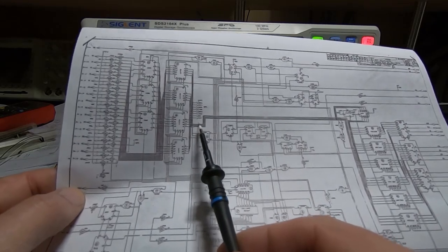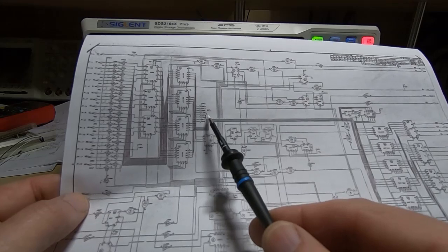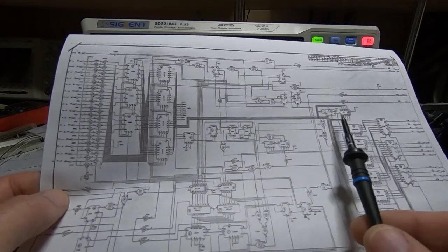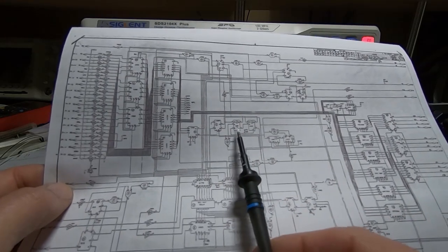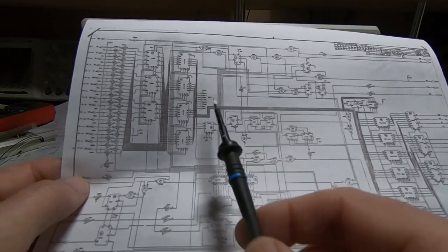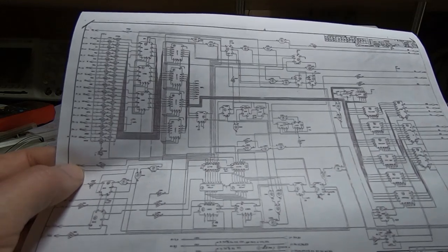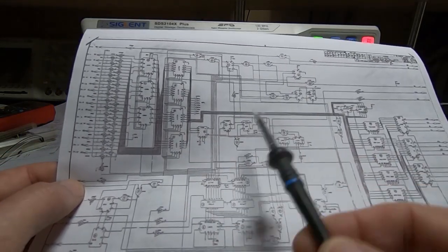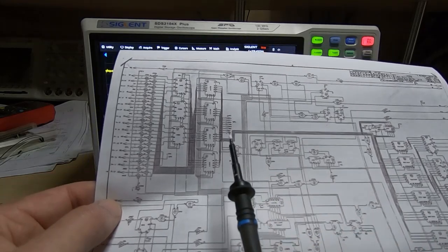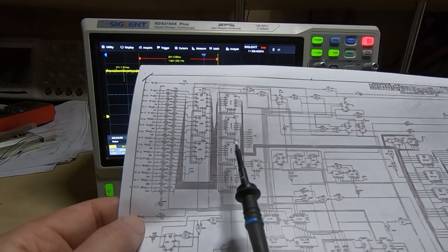You may also recall in the previous video that when we first started looking at this, we had alternating lines. One line was showing a block of solid characters, the next was showing random text, the next was solid blocks. It was alternating between the two. And that's the kind of effect you would get if one of these pairs wasn't doing what it was supposed to. So all these clues kind of add together and point you in the right direction. But what I want to do now is attach the logic analyzer.